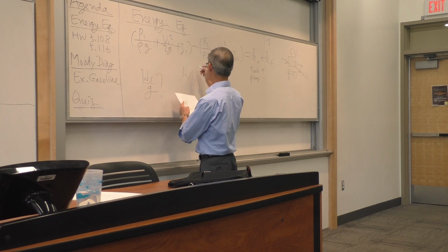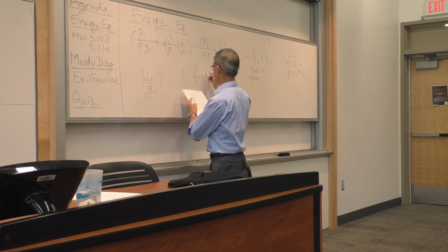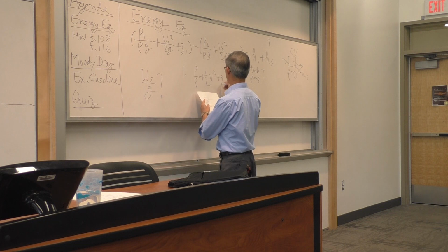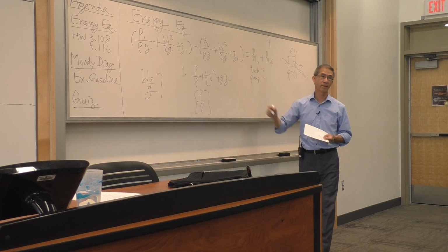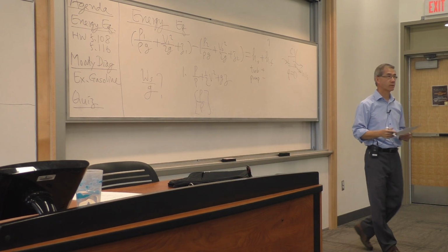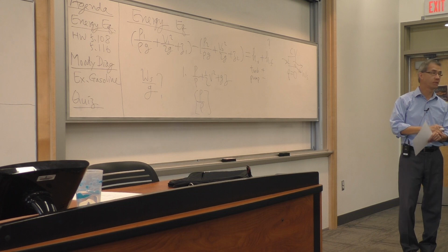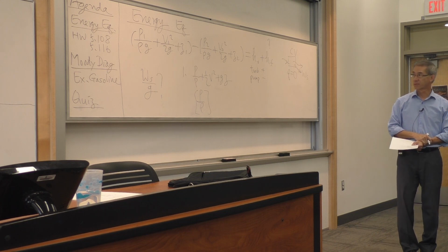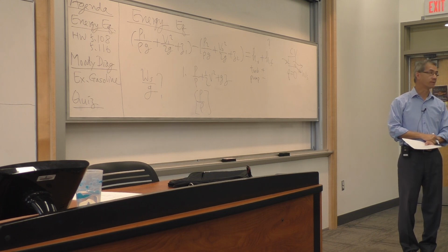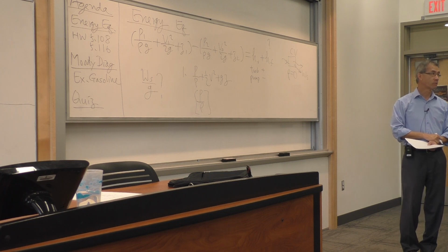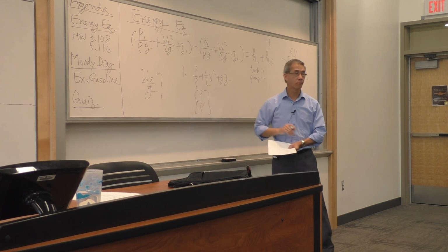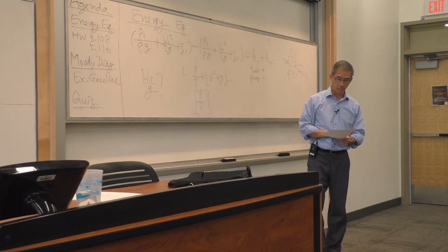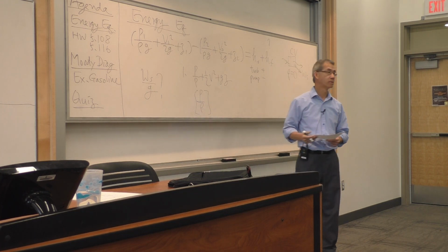First part is: tell me, when the equation of energy, or even Bernoulli, because they are all in the same form for this, just P plus half rho V squared plus rho g z, what is the physical meaning, physical interpretation of a term that has pressure over rho, which by itself is by no means transparent.